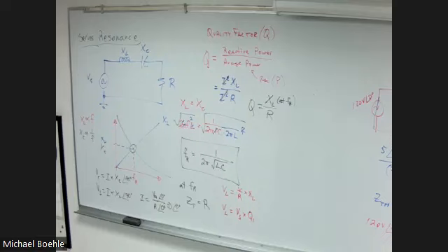For your lab, I think you apply like 4 volts peak to peak. And I think the Q of our circuit's around 2.5 or 3 or something. So you're going to get a higher voltage out than you put in when you measure. That's kind of a neat thing, right? Up to a point.